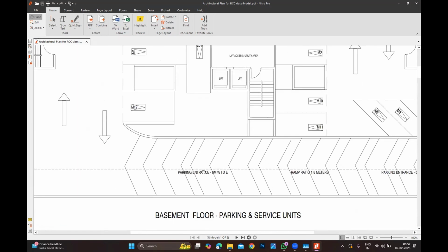In one slab, both entry and exit. Okay. The mall will have the entry on one side, the exit on the other side. If you go to any other mall, it will have a wider one. This will make a drastic difference in structure. Which one is more favorable? This is more favorable to structure, because you have one area and you can easily place the columns. Easily place the columns in other areas. If you do have two ramps, placing the columns is difficult.